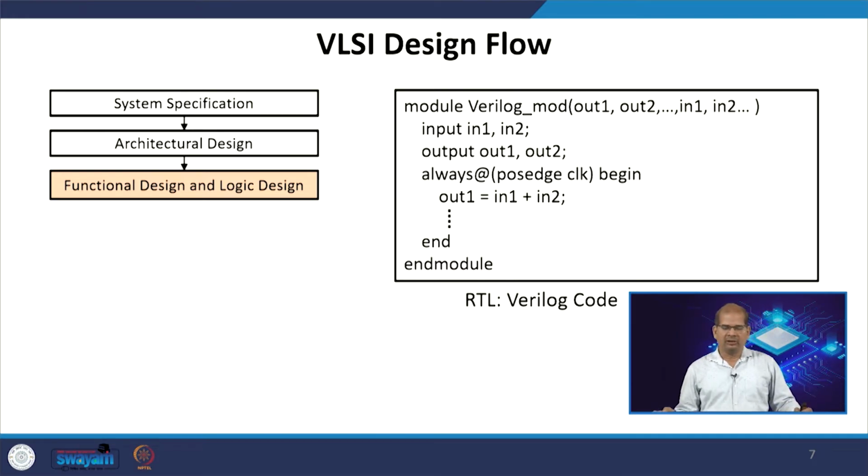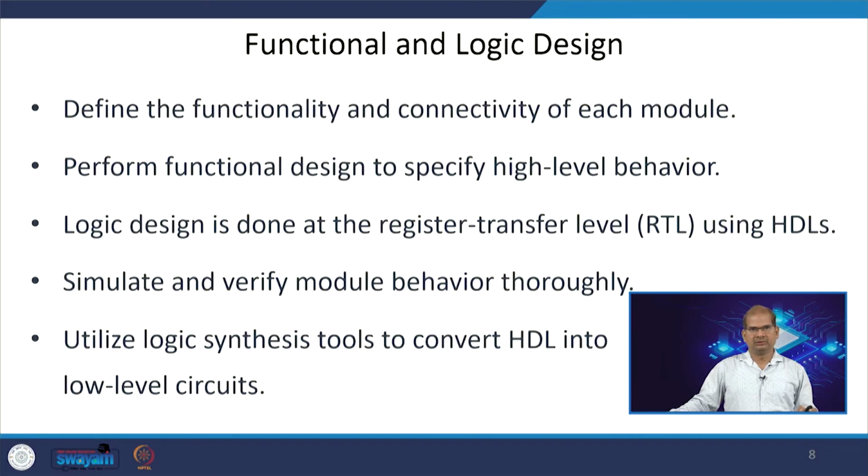Now, look into the RTL. The Verilog needs to be designed, that is, how you functionally implement the design. The functional design needs to be implemented using some form of register transfer level. This is the Verilog code, which will be written in a high level language, where we implement the system specification and the architectural design in more detail, represented in terms of a hardware description language.